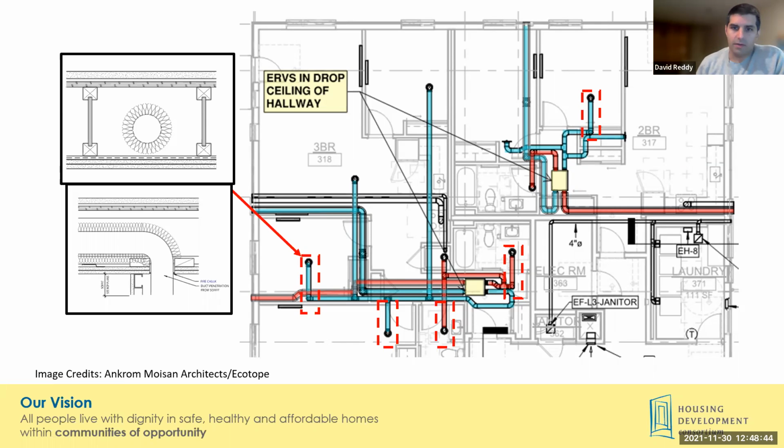But one aspect to consider is to eliminate that additional duct, as Alistair had mentioned, by using a ventless dryer. That's the exemplary building recommendation. And again, ducting the exhaust to the exterior for the range hood, especially in these units where it's anticipated that a lot of cooking will be occurring.